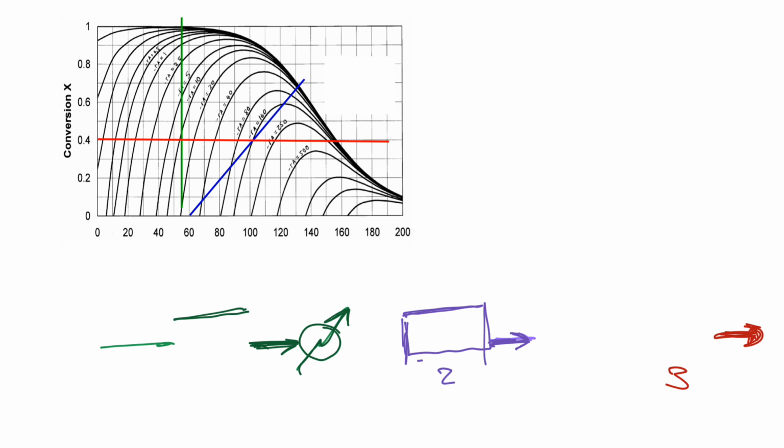One suggestion discussed by Vogler is to operate a few adiabatic CSTRs in series. There is no heat flow to or from the reactors themselves, so they will follow the adiabatic energy balance when we consider the change in temperature versus conversion over each of the reactors. And then we have an intercooler, where no reaction takes place, between the reactors, with heat exchangers to reduce the inlet temperature to the next reactor so that it can climb up this hill.